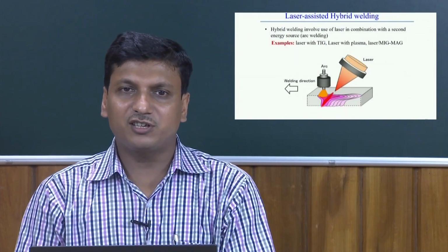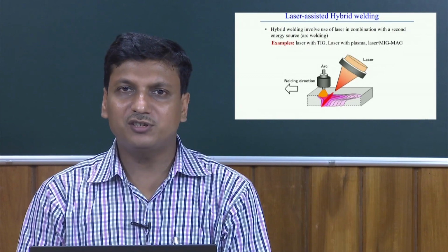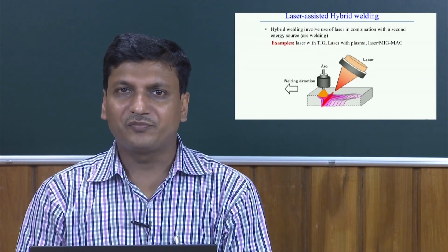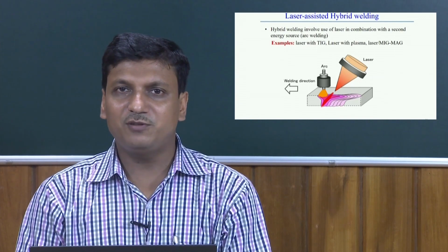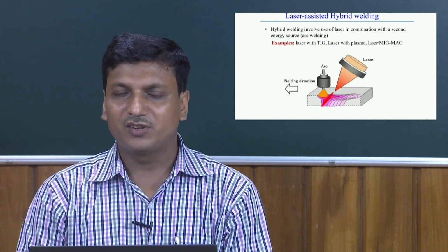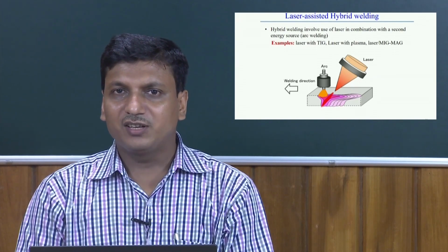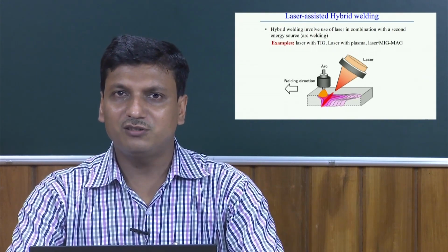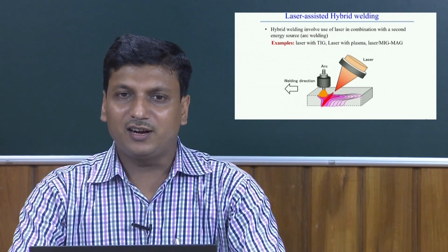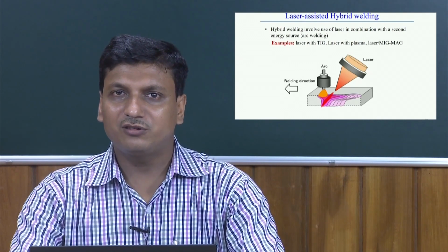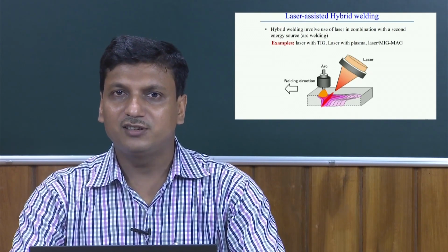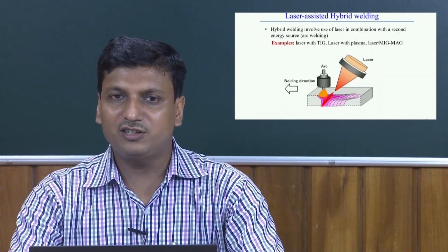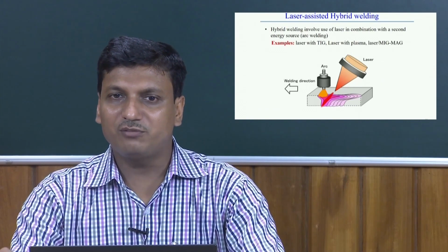But the main concern in this case is how the arc interacts with the laser, and how both benefit with respect to each other. The arc facilitates the formation of the keyhole, and at the same time the keyhole also helps to stabilize the arc by providing extra heat energy within the zone of interest.